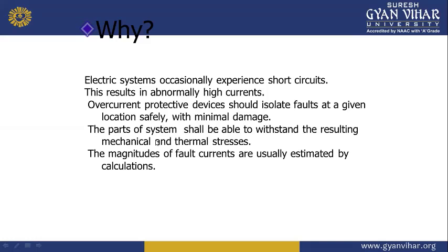The reactance of the circuit model of the machine changes in the first few cycles from low sub-transient reactance to higher transient values, and finally settles at a still higher synchronous, or steady state, value.